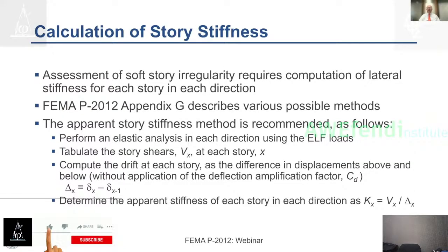Before we can consider these vertical issues, though, we need to get on the same page on how to calculate story stiffness and story strength. Those are simple words, perhaps, but there's a lot of disparity in the way that people might think about those calculations. ASCE 7 doesn't entirely tell you how to calculate story stiffness or story strength. So our project undertook a careful consideration of this so that we could give you some better direction.